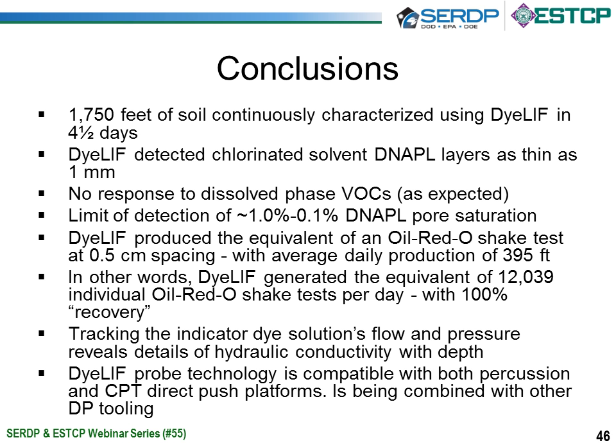There is no response to dissolved phase VOCs, which is totally expected, and that's a benefit of this particular technology if you're really trying to identify if you have DNAPL, where it is, or confirm that you don't have it. The limit of detection is between 1 and 0.1% of the DNAPL pore saturation at this particular site.